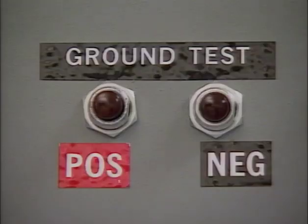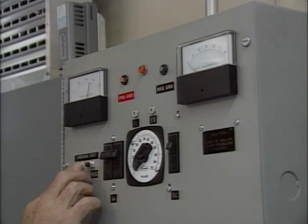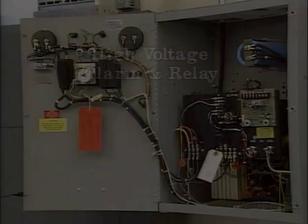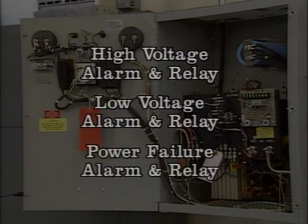This charger also has positive and negative ground test buttons. Each button, when pressed, will introduce a ground in its respective part of the system. The buttons may be used to check that the ground fault detection system and lights are functioning properly. Finally, a charger may contain a variety of alarms and relays, including a high voltage alarm and relay, a low voltage alarm and relay, and a power failure alarm and relay.